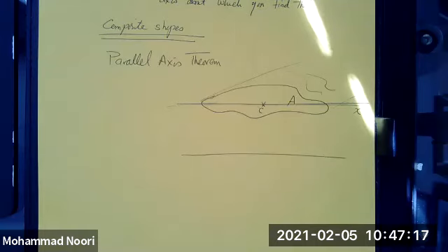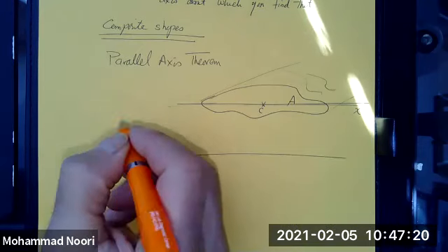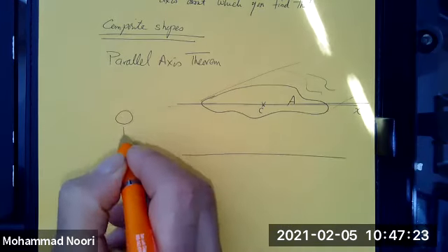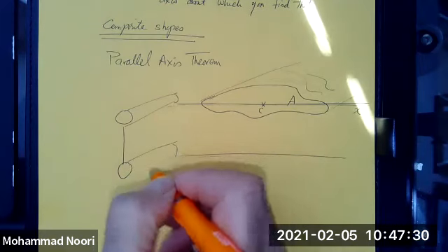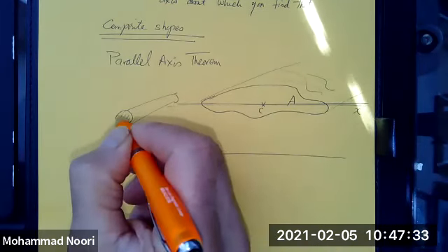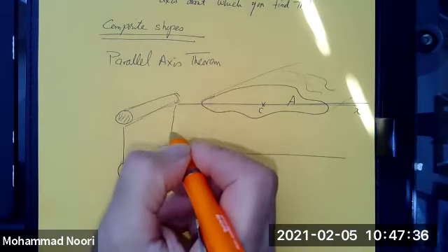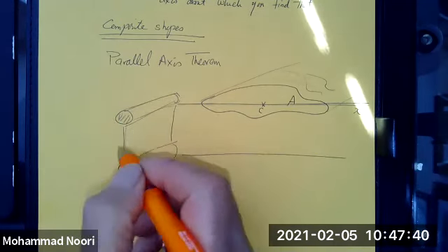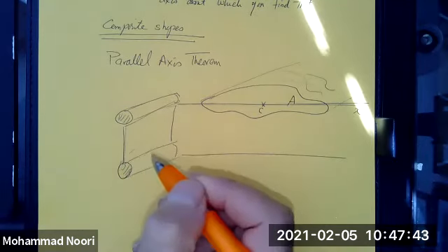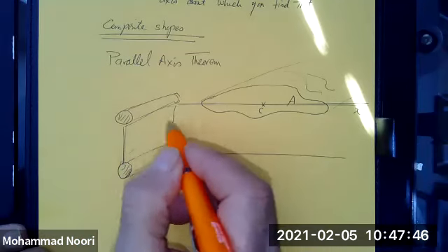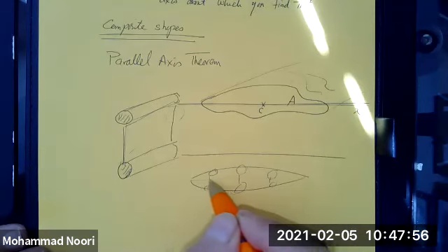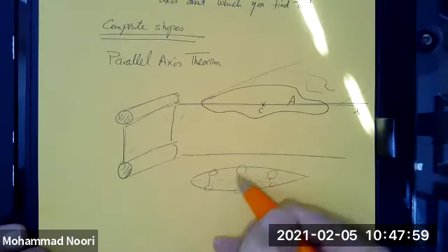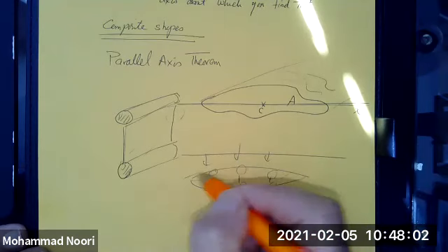wing of an airplane, the components that go into that, there's a component they call stringers. The stringers are sort of, for lack of a better word, I-beams like this. You have these solid tubes connected with a very thin layer of metal, okay? And you have a bunch of these inside the wing. It is a lightweight structure. So the load obviously applies like this, okay?